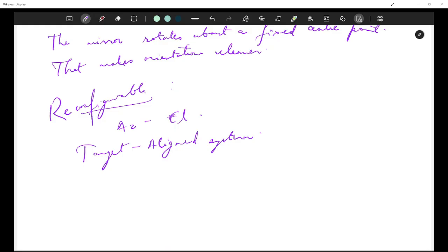So what do you think? Which would be better, RPS or UPU? You may think a parallel manipulator is perfect. But let's compare it to serial manipulators. Parallel manipulators are very sensitive to manufacturing tolerance. They have joint play and there are calibration errors. So high stiffness alone is not enough. Precision manufacturing is very critical here. Okay, this was very important.